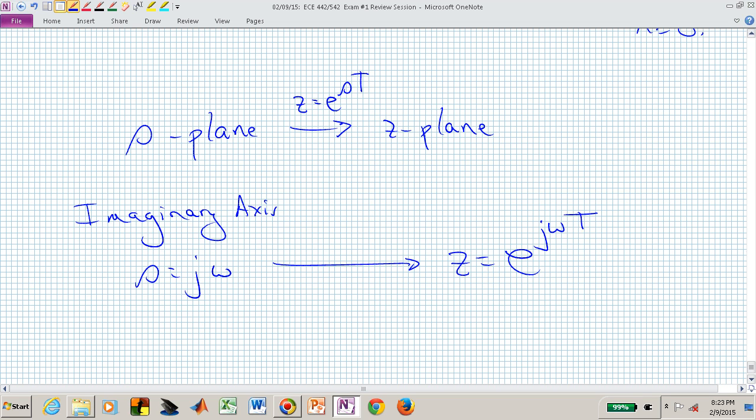But for now, this is the main connection, but you should be able to take any S-plane point and map it into the Z-plane, just using that relationship. And that we derived or connected because we said a unit delay, z to the minus 1, is like a delay of e to the minus sT in the S-plane. And that made our connection with S and Z.